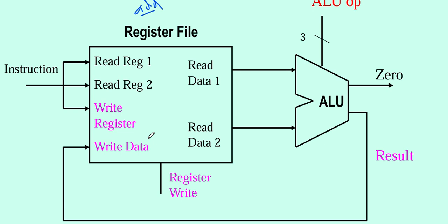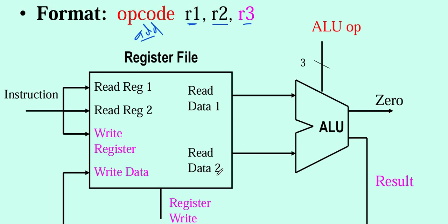Is this an I type instruction? Is this an R type instruction? Is it a J type instruction? So for example, I know that a J type instruction, for a single cycle data path, will not require the full ALU to do the computation of the address, right? Now, I also know that for an I type instruction, we will not read the second operand from the read data, right?